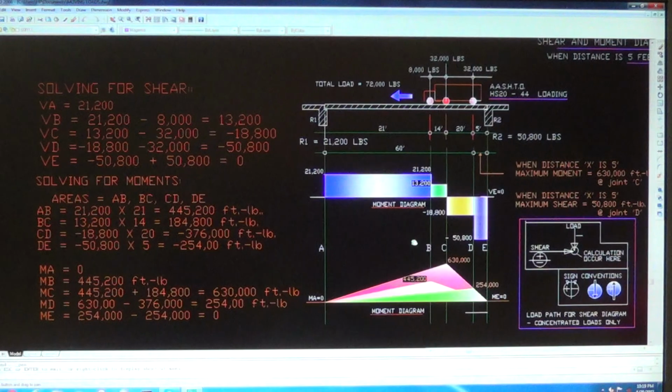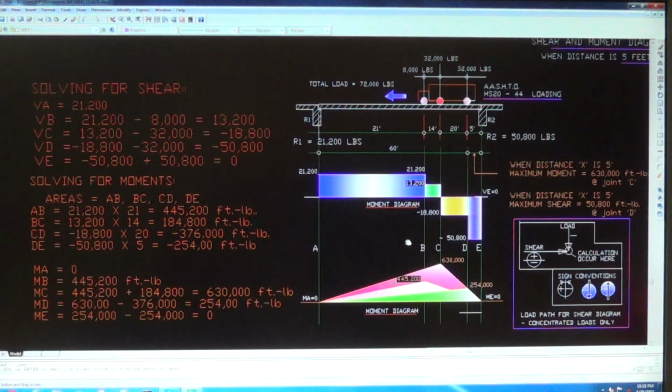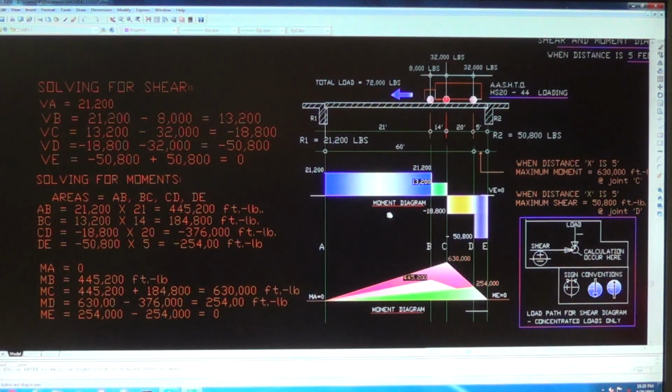Now let's go to solve for the shear. Okay, the shear diagram. Start with the reaction, 21,200. You gotta calibrate this line and locate the point of 21,200. So that's I located the 21,200 line, and now that is the shear at A. Okay, starts with that reaction there.